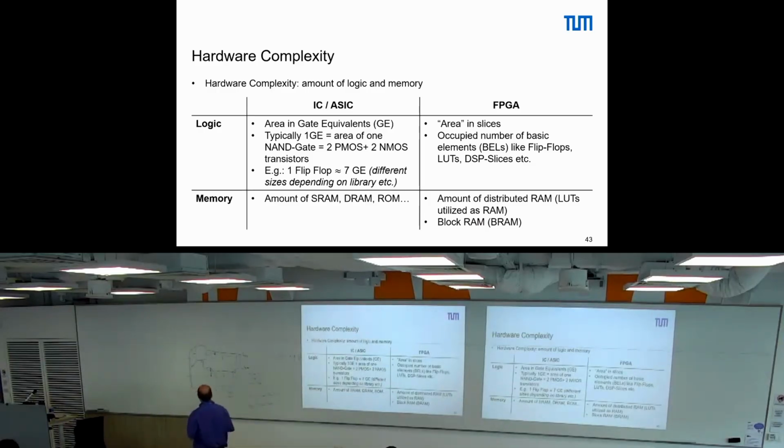Okay? Where you mean here? If we would add it here, well, what would we win? So this register here allows us to have one clock cycle to process the inversion and one clock cycle to process the OR. Right? If we would add it afterwards here, what would we win? Let's say we skip them, then we have the critical path now from here to the register here. If we have an additional one, well, we have one delay for this OR still as before, and the delay of this wire here, so we will not win anything. Okay, good. Questions to this? Good.